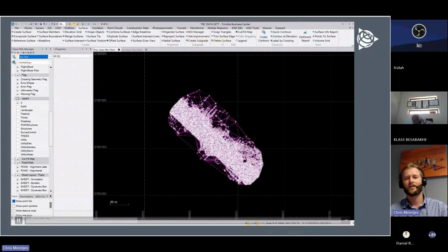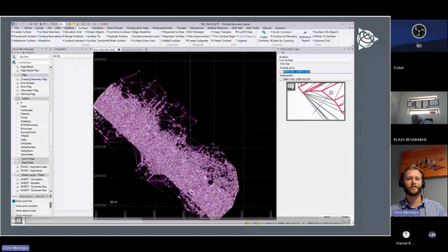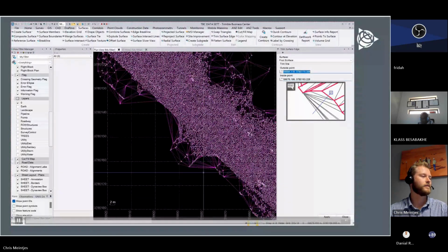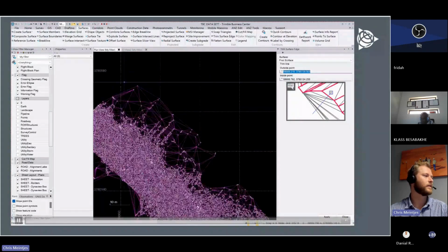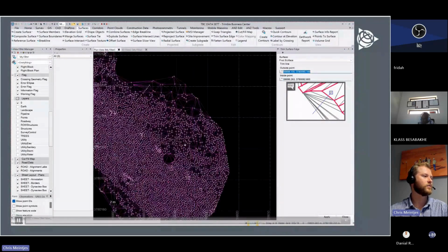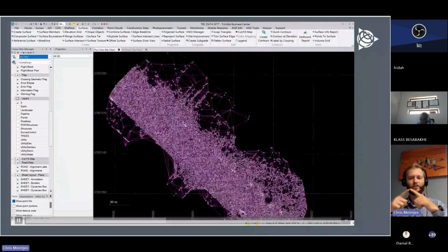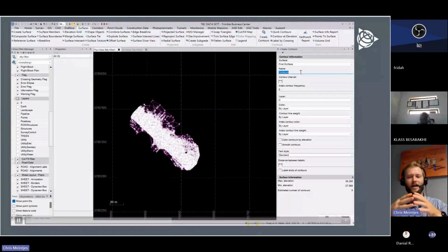Obviously, as you know, you can edit the maximum length of a triangle, so it just won't draw triangles between certain points, or you can just trim the ones that you don't want there. So you can see I'm just editing. I should have trimmed them a little bit better, but it was just for demonstration purposes that this tool works, although it will not trim a triangle so as to leave a tacky point no longer connected by 2 points. So it's important to remember that if you have an outlier point that it's drawing triangles to and you don't want the triangles there, it's better just to delete the point than to try to delete the triangles. They'll never go anywhere.